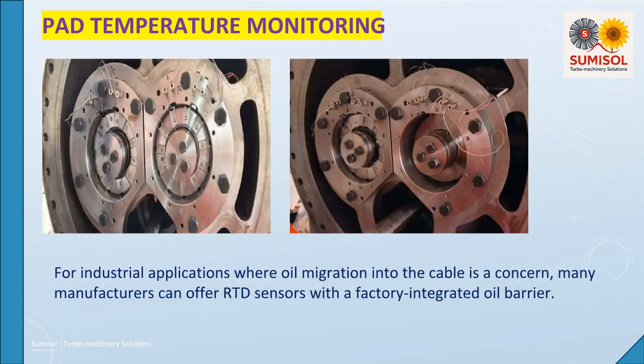Thrust pad RTD must be secured with RTV sealant compatible to withstand a minimum of 120 degrees Celsius. Note that if we use a high-temperature range sealant, curing time will be longer. RTD cables are to be properly secured, and strapping to be done with temperature-compatible straps. Continuity and polarity of RTD and displacement sensor cables are to be checked and recorded in the service report.